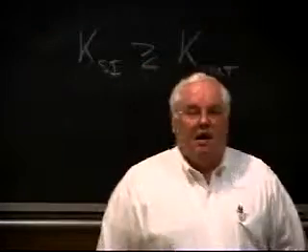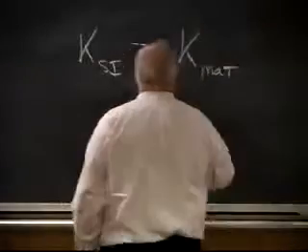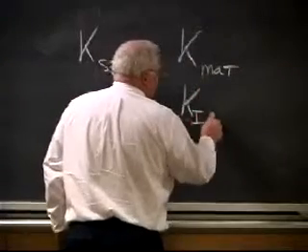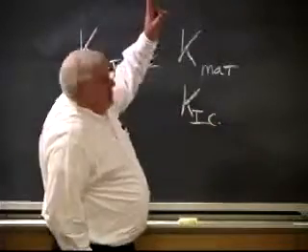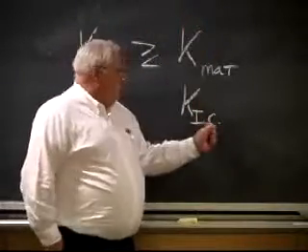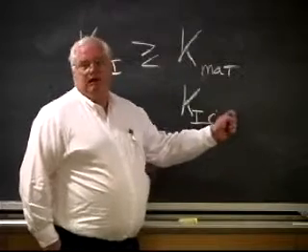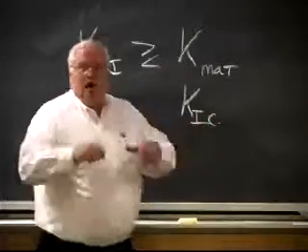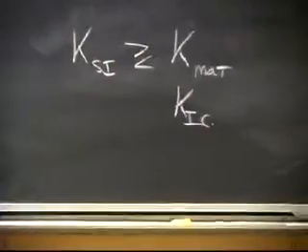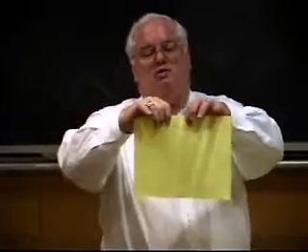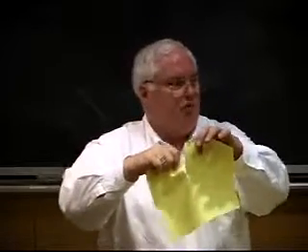That's KIC, right? That's what the material property is usually, K1C, C for critical. Also, sometimes instead of A up there, they use C for the crack length. So some people may say K1C as the critical crack size, but basically it's critical. K1 is mode 1, which is pure tension. K2 is shear. And K3, let's see, I may get 2 and 3 backwards. If I remember, K1 is this way, K2, I think, is this way, and K3 is shearing, pushing one down and pulling one up.